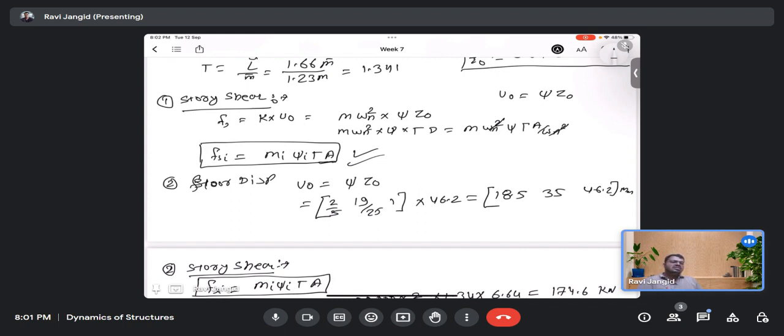The outer diameter is given for finding y. It is given as 168.3, so if you divide it by 2 you get y, the extreme fiber distance, and I is the 174 given to you. Then you can calculate sigma.